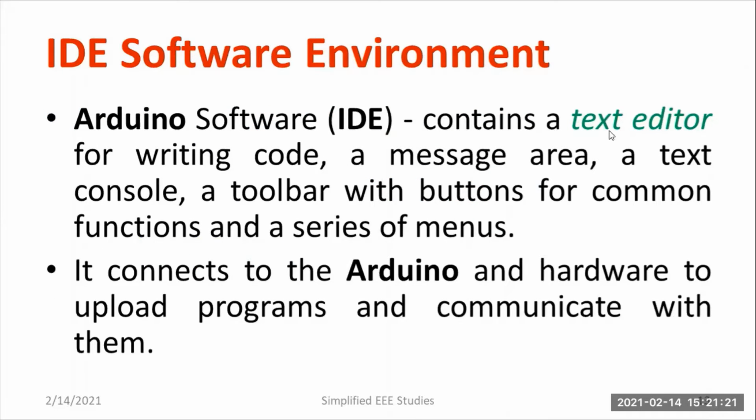It contains a text editor where you can write the code. Then there is a message area. Then a text console is also available. Then there is a toolbar. So it is very easy to execute the program. It connects to Arduino and you can upload the program to the hardware and the execution can be done. Clear? So proper communication can be done in a very easy manner. The hardware should be connected to your USB port. Then you have to burn the program, save the program in the hardware and execute. It will be very easy.